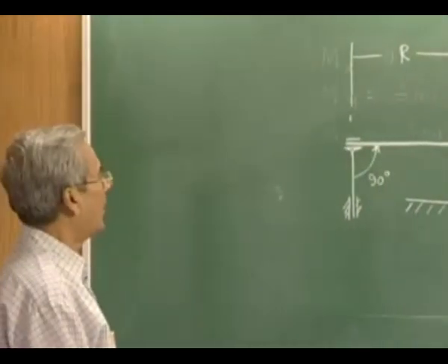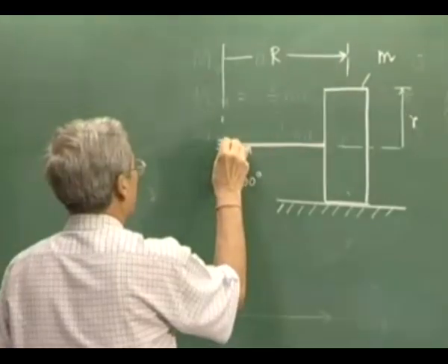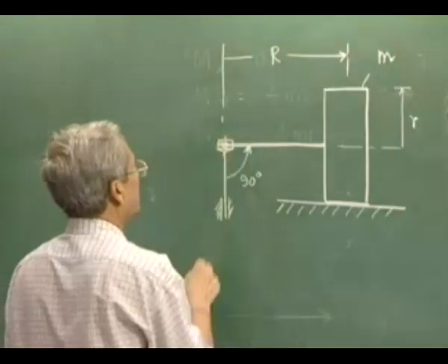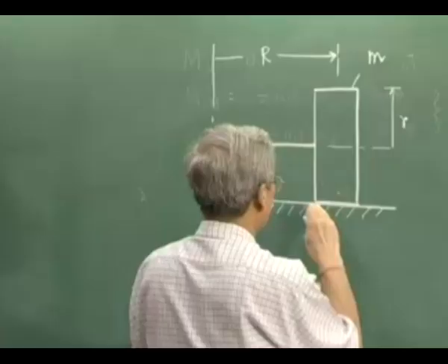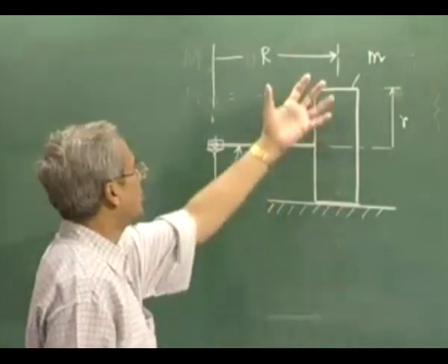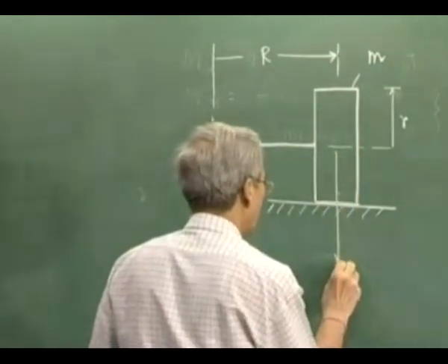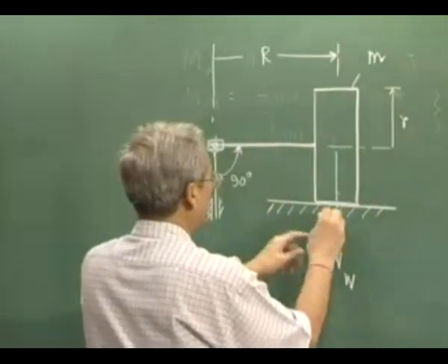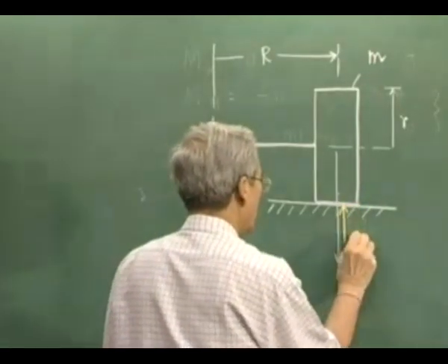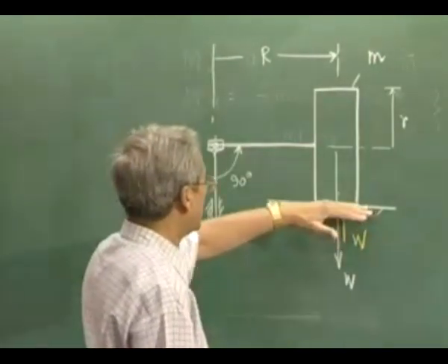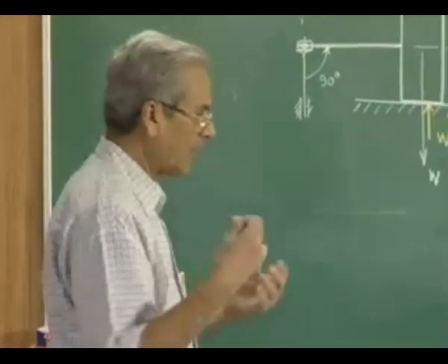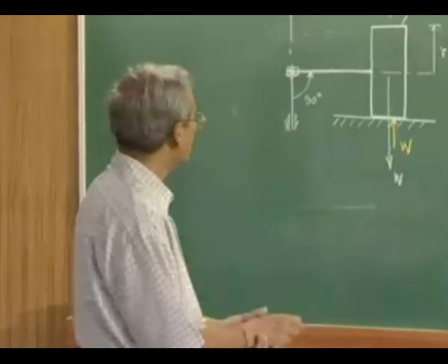So what we expect, and this is hinged here, is that the total force acting here will simply be the weight of this, if we ignore the weight of the arms, etc. So if the weight of the disc is W, then the reaction between the floor of the crusher and the crushing roller will simply be W. So this weight will be just balanced by this, and the crushing force will be W. So if we call it a 10-ton crusher, it means that the roller has a 10-ton weight, and it can produce a total crushing force at the contact point below.